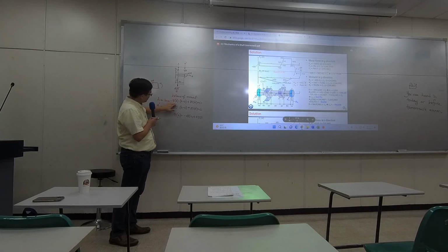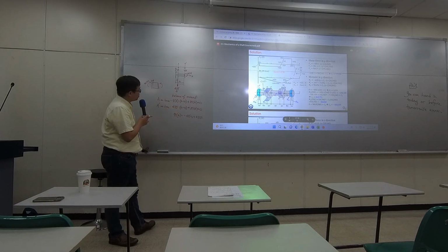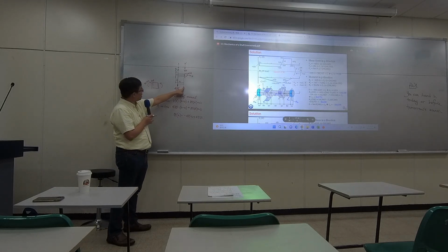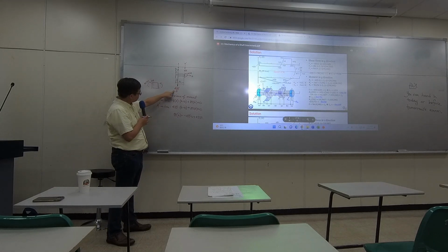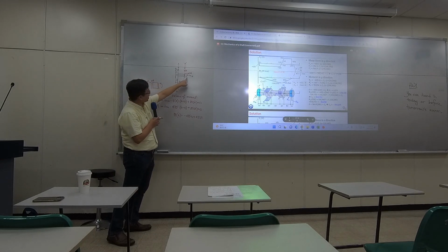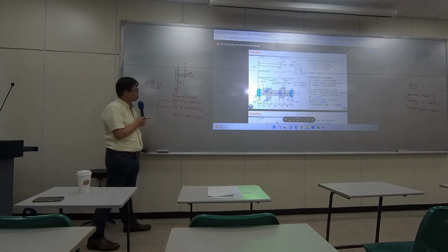So the entire counterclockwise moment sum together equals 0. If you choose A prime as a base, this 435 gives you counterclockwise moment, and also Mx has counterclockwise moment. So summing up, that equals 0.